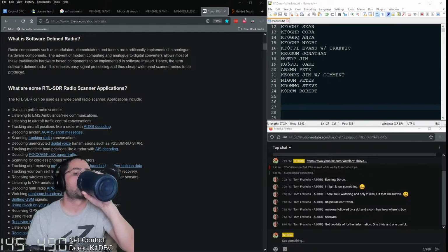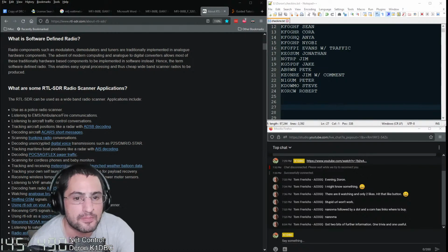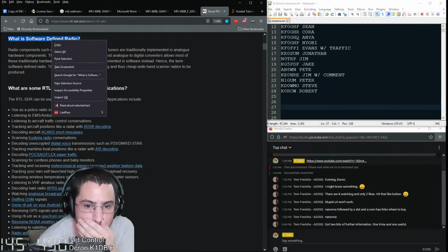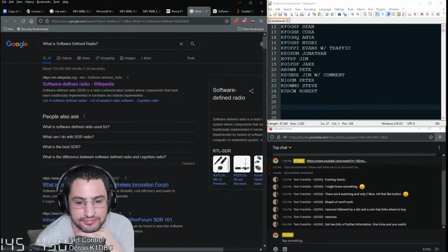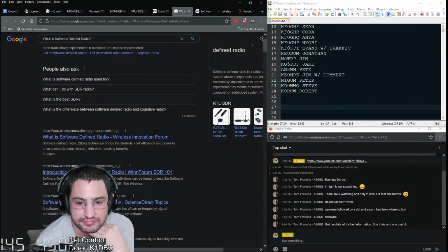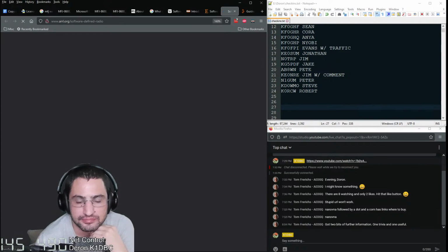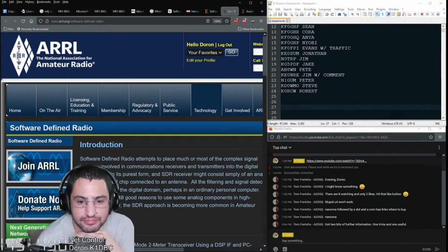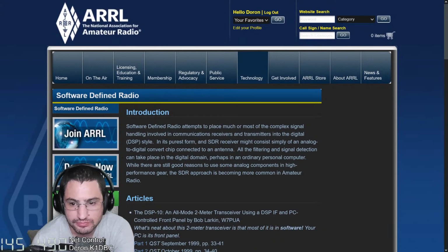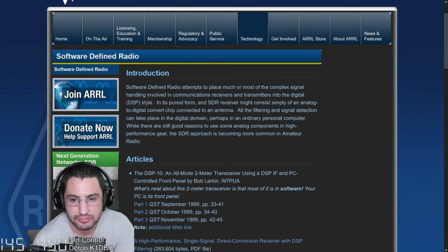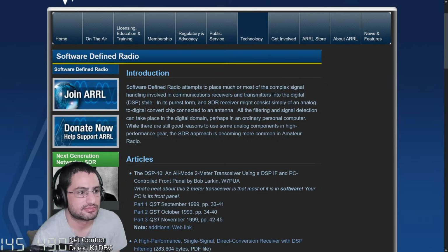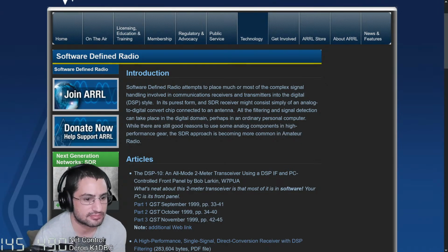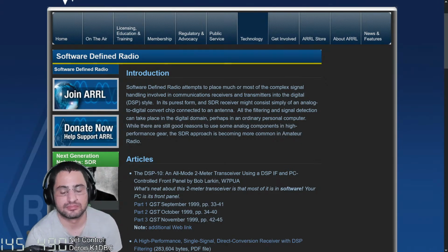Jonathan, the big thing between software-defined radio and the superhet that you're probably using right now is that very early in the process the signal is converted from an analog signal to a digital signal. That is to say, it's turned into numbers. And from there on, all the rest of the processing, like the mixing, is done as a mathematical function, on the numbers.